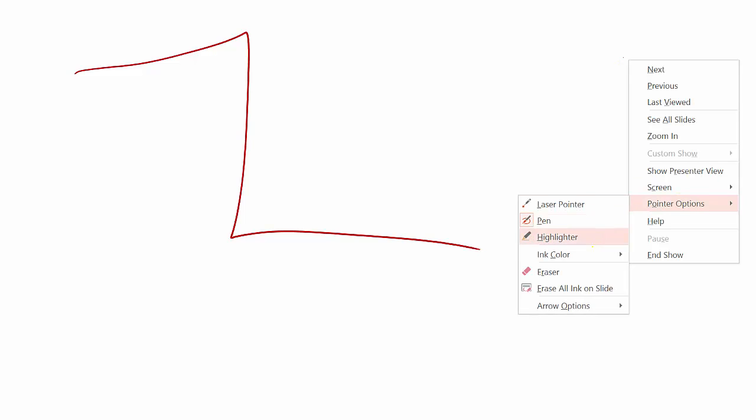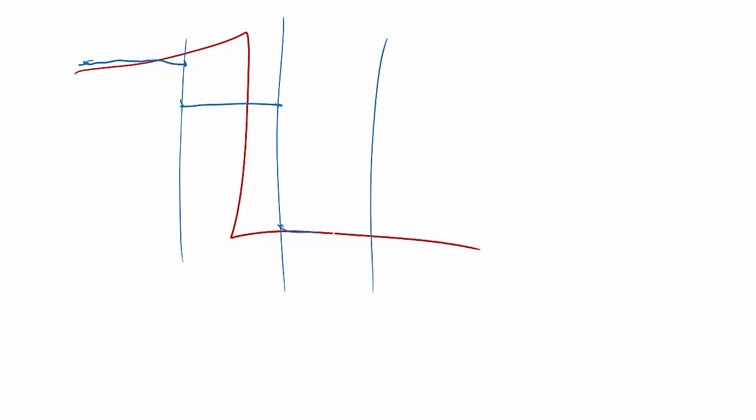In finite volume, because you only approximate the volume integrals, you're going to have averages like this. Okay, I didn't draw it very well. And in this interval, you would have something more like this. And in this interval, you have something like this. So if you plot the solution as points, it will look like this. So it kind of looks smeared, right?